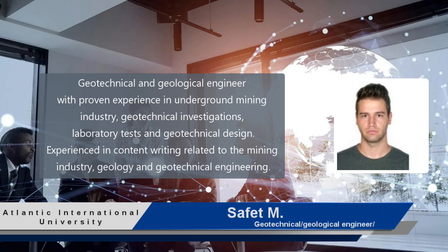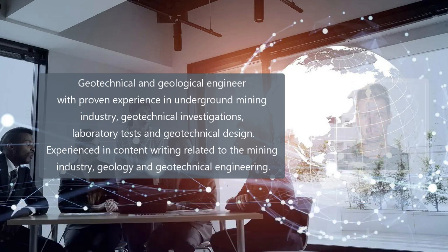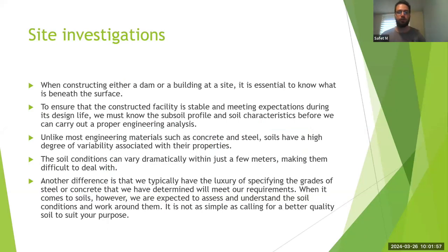So what exactly is site investigation? If you want to construct something, such as a building or a slope on a highway, it's essential to know what's beneath the surface. That's the most important thing for the civil engineer, the geotechnical engineer, or the geologist, to ensure that the construction facility is stable and meets expectations during its design life. We must know the subsoil profile and the soil characteristics before we can carry out a proper engineering analysis.